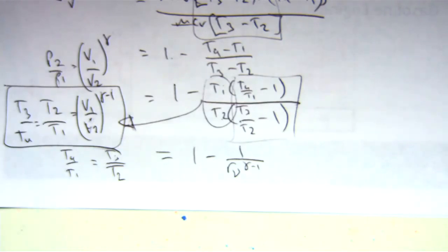You will find the place where gamma turns up in our equations will be because we've had to look at an adiabatic process. And the places in these cycles that we look at adiabatic processes are the isentropic processes, because they're adiabatic and reversible. Okay? So that's where the terms pop up, and once they're in, now I express the efficiency of the whole cycle, which includes non-adiabatic processes. But I've got a gamma term in there because of all the derivation that's crossed things off. Okay?